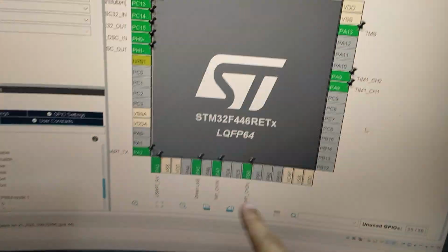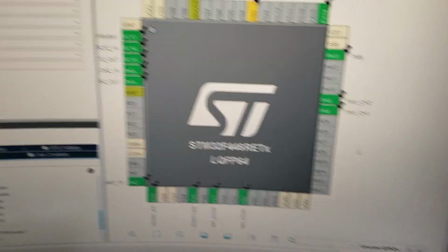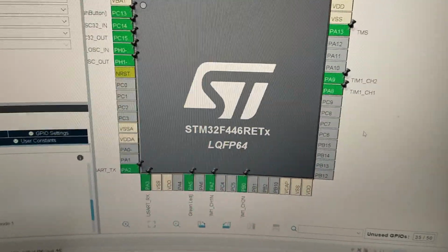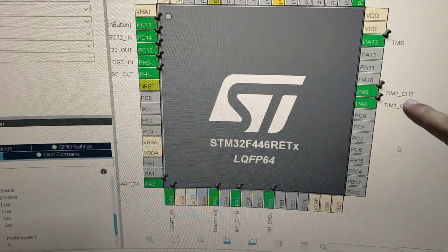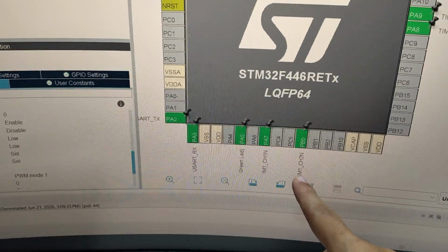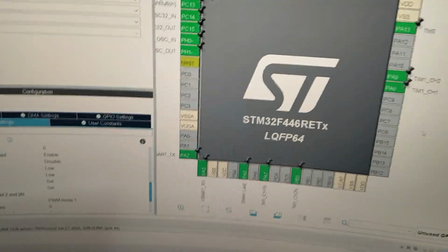I won't really go into those details, but yeah, those are the two PWM channels which we were using to drive our opto, right? So now we need another channel. Since now we need 4 total PWM outputs, we can use timer 1 channel 2, like I'm doing here, and along with that, timer 2 channel 2N similarly. So now you can see we have 4 PWM signals basically.